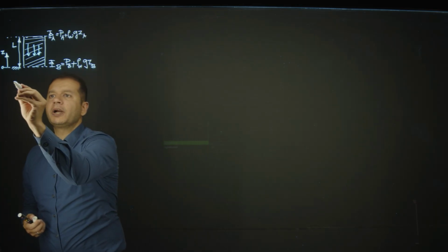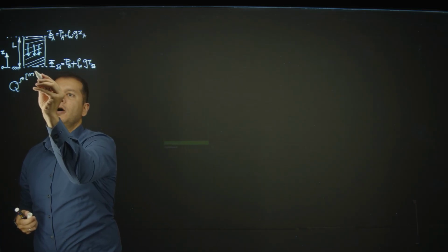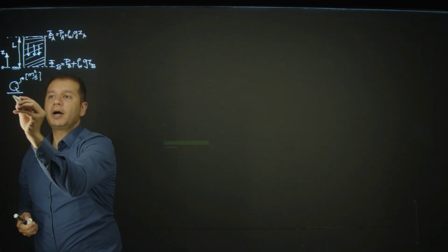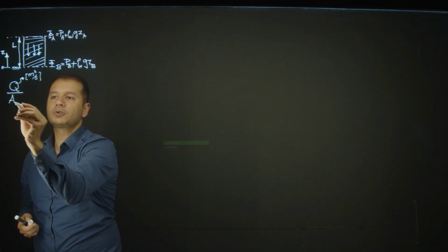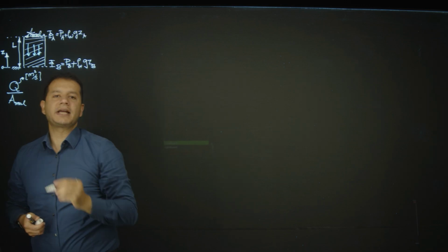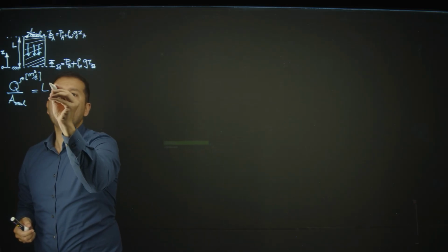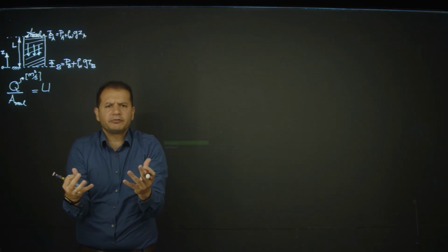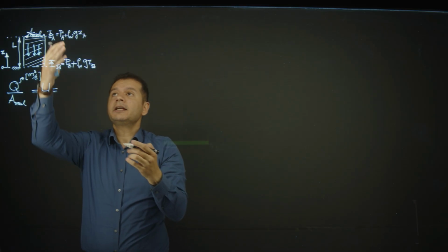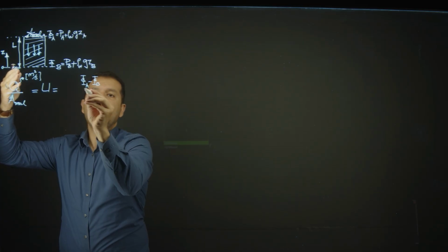Darcy said the flow rate that happens through this system, the volumetric flow rate that has the dimension of cubic meter per second, if divided by the total cross-section area A total, the cross-section area of this sample, which is pi r square, the radius of it, that can be defined as an average velocity u, which is the velocity of nothing, is superficial velocity, so we call it Darcy velocity, for example, and that is proportional, naturally, to the difference of the potential that the points A and B have and how far they are from each other.